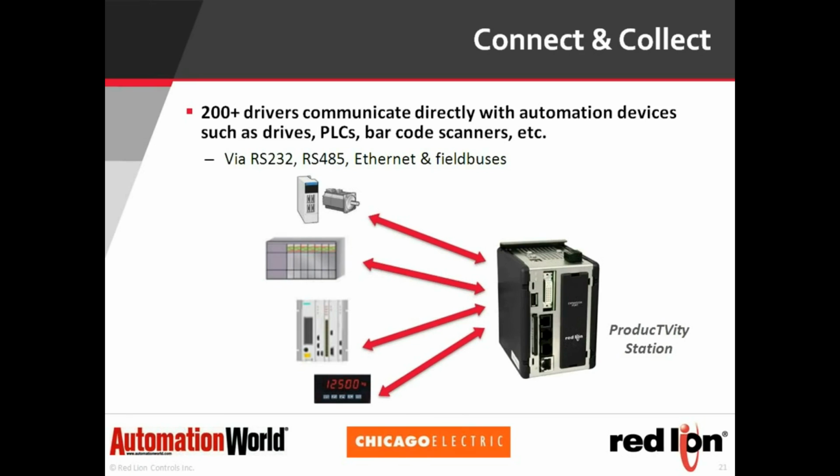Do you have PLCs from a single manufacturer? Are the drives from the same manufacturer? How about the panel meters, the temperature controllers, etc.? If they're all from the same manufacturer, you might be in good shape. If they're from disparate manufacturers, then you've got to think long and hard about how you're going to get that data out of those systems.